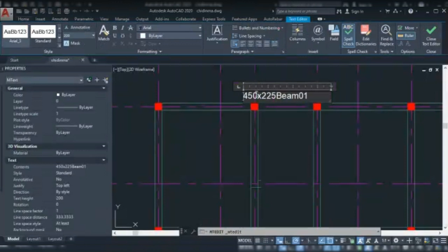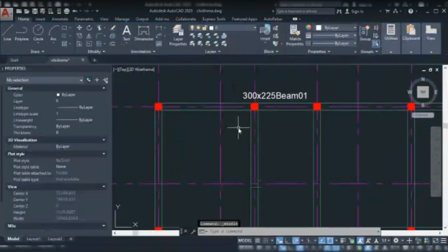So, since it's a roof beam, it's carrying only the roof. It's a very small load. It's not that it's very small, but it's small compared to other ones. So we can actually reduce the depth of the beam to 300, because it's a roof beam. Okay.